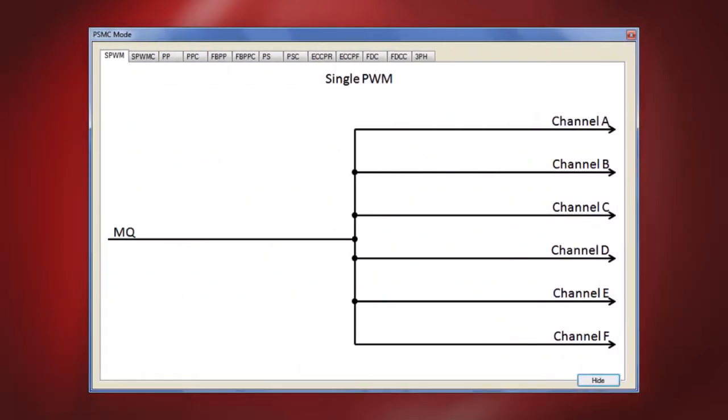The mode control block is the heart of the PSMC PWM module. This forms the basis on which type of 16-bit PWM is decided and derived from the PSMC peripheral. Peripheral capabilities range from simple single-channel PWM generation to multi-channel complementary waveforms with deadbands between transitions. Let's look at a few of the important modes of the PWM and the intended applications which can benefit from these modes. There are 5 fundamental modes of operation, 1 high-resolution frequency mode, and 1 6-step mode that simplifies steering pairs of outputs to the 6 PWM channels.